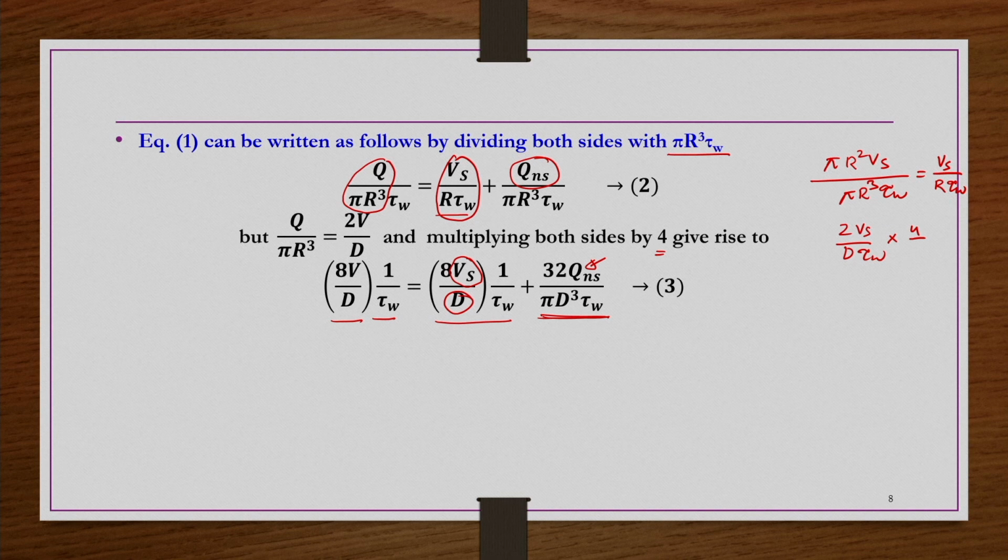So, we are taking the cases where there is wall slippage. Remember, if you have a large diameter capillary, then wall slippage may be very small, and you may avoid it. But when you take large diameter capillaries, then shear stress and shear rate both will change from center to wall. So, you cannot assign one single value of shear stress or shear rate.